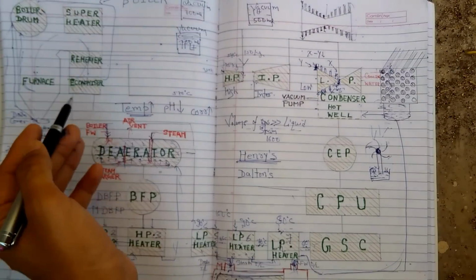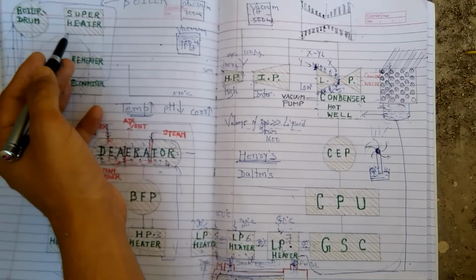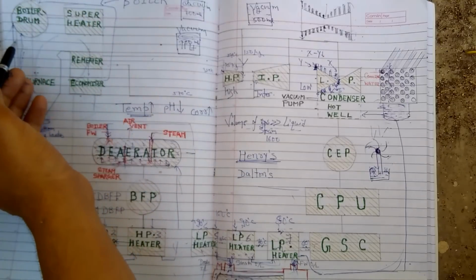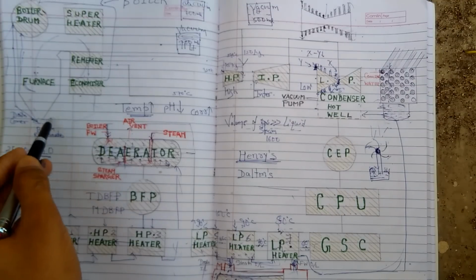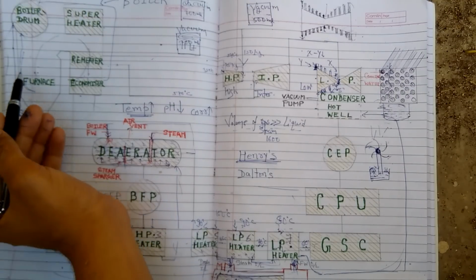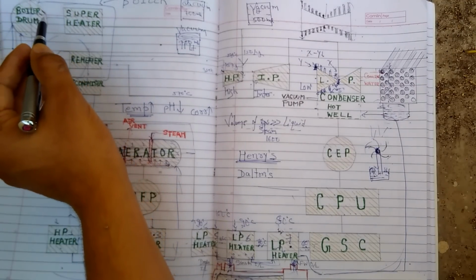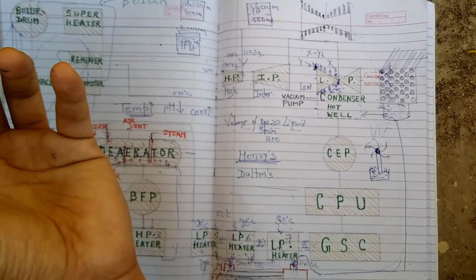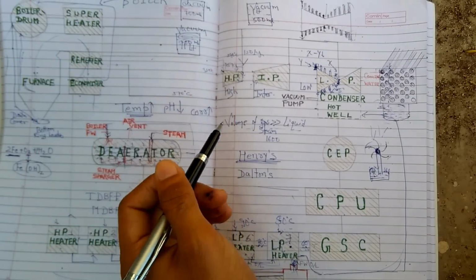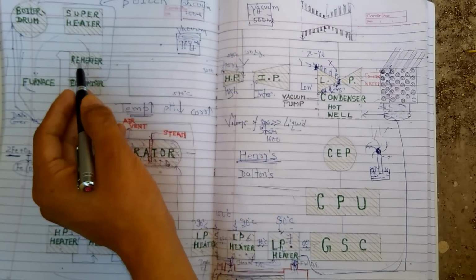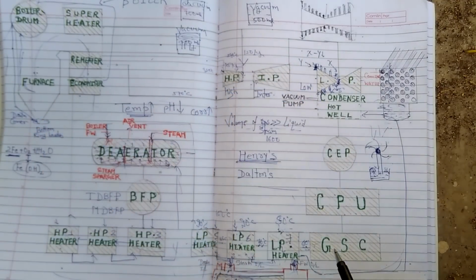Again I increase some temperature, then send it to the economiser, and here again I increase the temperature of the feed water by using the flue gases. Then after the economiser, send it to the boiler drum if it is a subcritical unit. Then through the downcomer it comes to the bottom ring headers, then it goes up to the boiler drum using the water walls. Then from the boiler drum I again need to superheat it to remove moisture. After the superheater, it does work on the HP turbine, reduces its pressure and temperature, again increases temperature in the reheater, and does work on the IP and LP turbines.